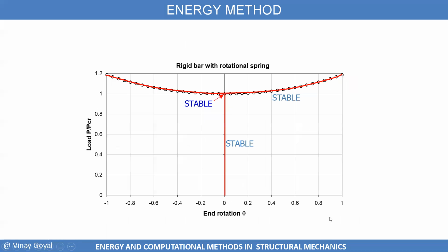So that's what we've done, and so now I can show it here completely. This point is stable and buckling occurs, and then I'm also stable in this whole regime. What does it mean? It means going back to the definitions. When I remove the load P, I expect the rigid bar to return back to the original state, right? That's what stability really meant there. We know that bifurcations are over here because I went from one equilibrium state, which is the rigid bar straight, to a deformed rigid bar at the pin. It rotated about the pin, but I know that's stable because when I remove the load, it can return back to the original state.